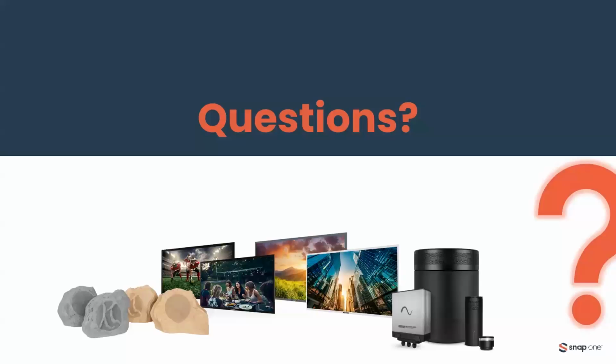I think one thing potentially, it's already understood, but going back to one of the comments, Brett, you were talking about with tap settings, just so everybody's aware that the purpose of the tap setting is, when you're doing 70-volt systems, all of your volume control is done in a single zone, so you don't have independent volume control by speaker. What the tap setting allows you to do is, depending on where you have to place the speaker relative to the listening area, let's just say you've got a fire pit area that forces you to push that speaker further away from the listening area than other speakers, you can actually increase the tap setting on that one, so the relative volume of that speaker is higher compared to others. The goal is that you're trying to create an even listening level no matter where you are in the system at the listening point, so you're adjusting the levels of each individual speaker. I just wanted to point out that's the intention behind the tap settings.